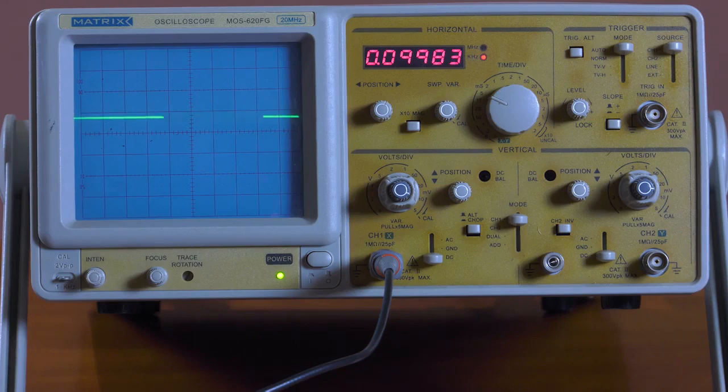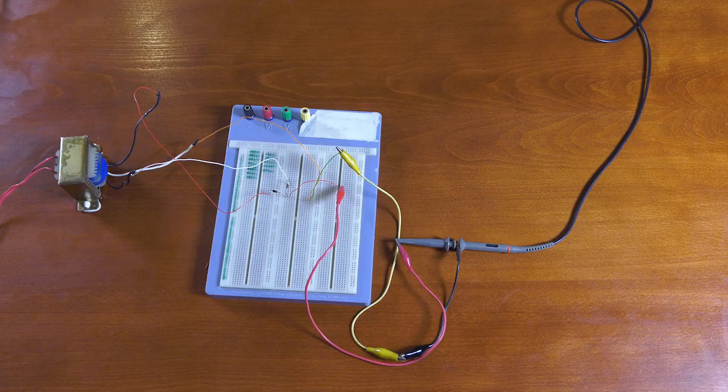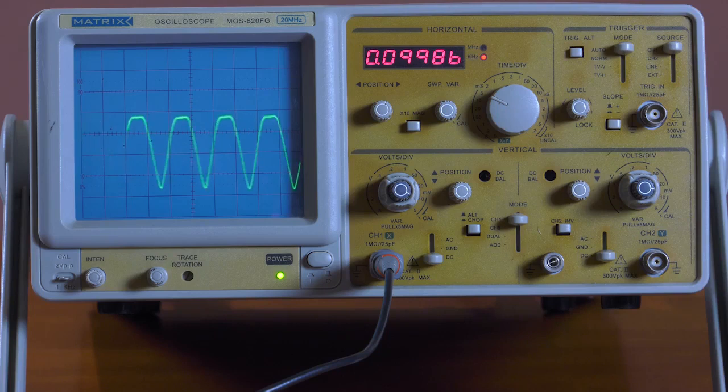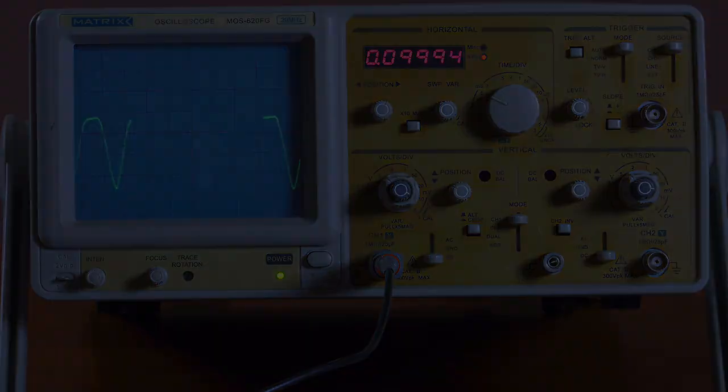If you wish to have a power supply that's 9 volts, you add a 7809 voltage regulator. If you wish to have a power supply that's 12 volts, you just add a 7812 voltage regulator. If you're looking to have a negative voltage, which operational amplifiers require, then you'll use a series called the 79 series. For positive regulation, you require the 78 series. For negative supplies, you require the 79 series.